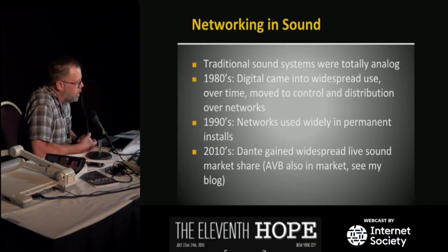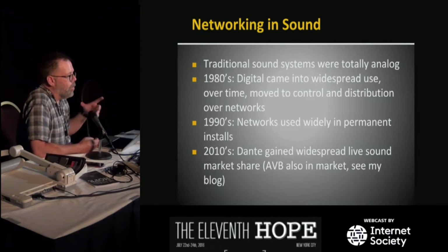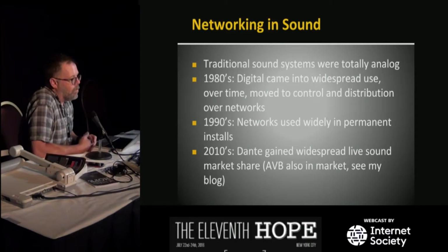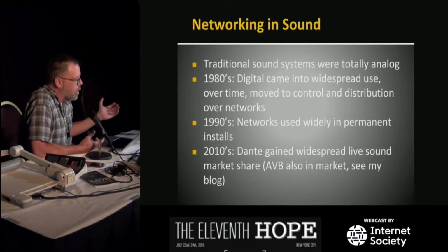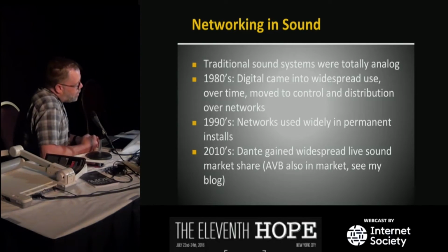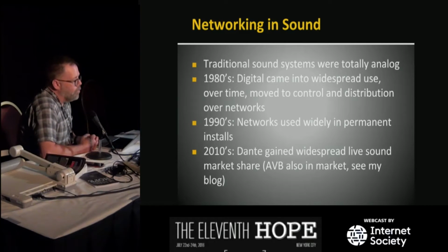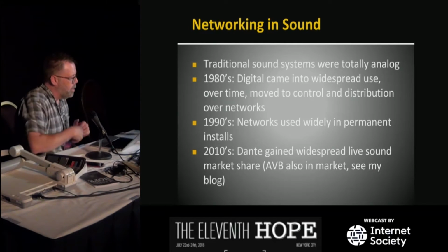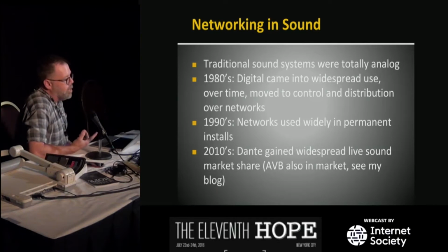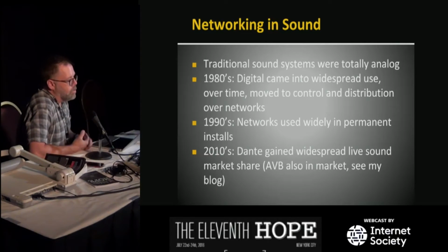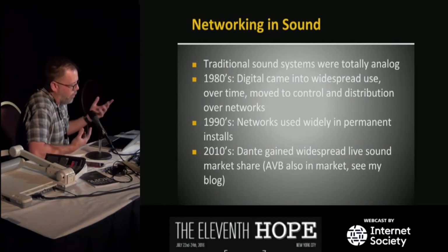And then just recently, this proprietary system called Dante, made by an Australian company called Audinate, was adopted by a number of the big manufacturers in the live sound market, and they have become the de facto standard. Another one that predated Dante a little bit was AVB, which is changing its name to TSN, time-sensitive networking. It was adopted by a couple of manufacturers, including the people who make these speakers. Meyer Sound was big in AVB, but at the big trade show this year they announced they're going to support Dante, so they'll have both.